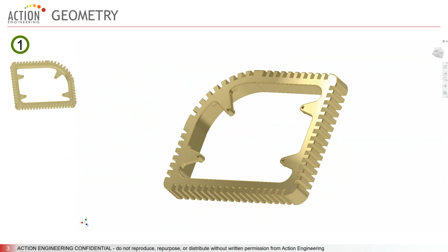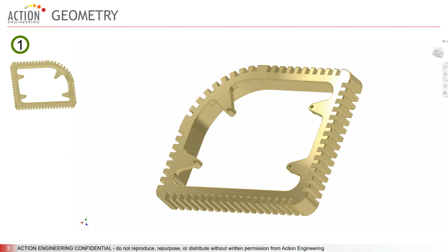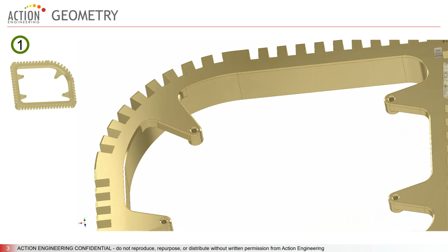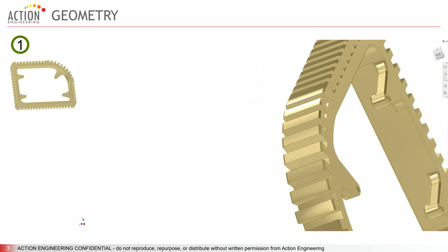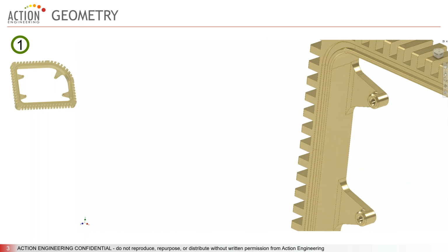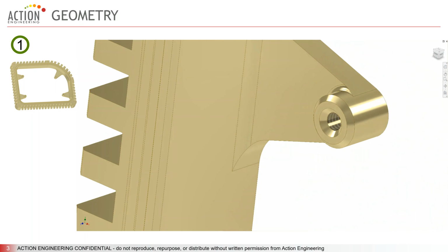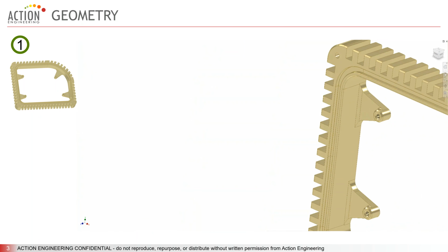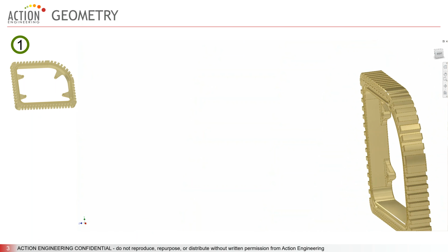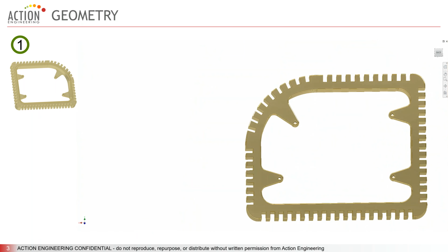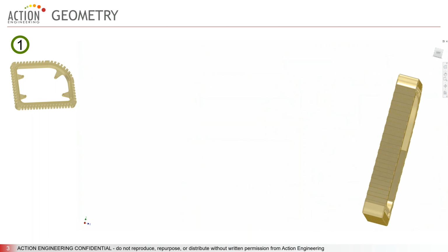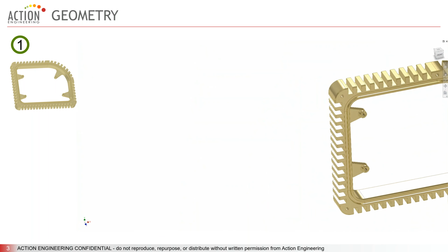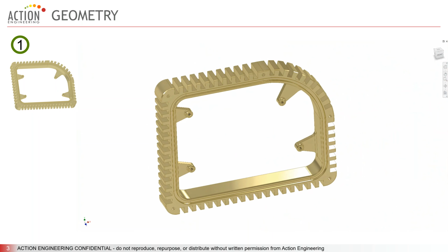When it comes to MBD, we know it is capturing the 3-dimensional mathematical functions and coordinates that represent the shape you want to build. Because the shape is digitally captured, for the cases where the 3D CAD is used directly to feed a CAM machine, we don't need to show the dimensions through an annotation or on a drawing. And if you're familiar with geometric tolerancing, then the 3D model becomes the basic dimensions.